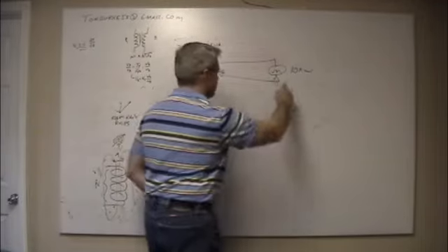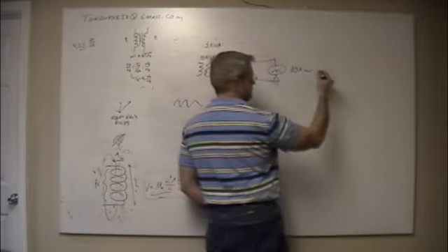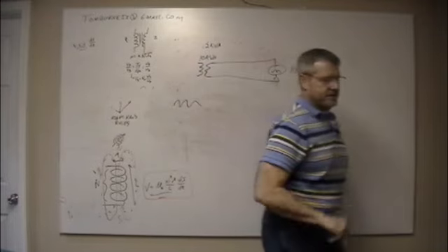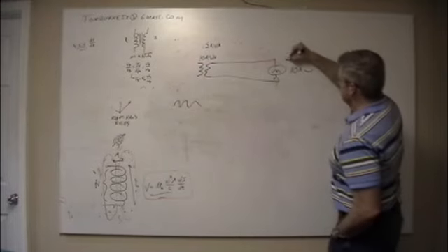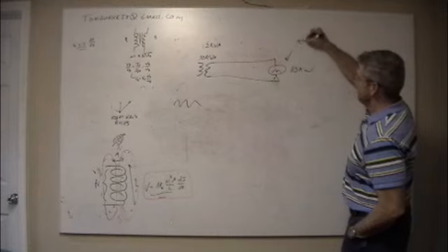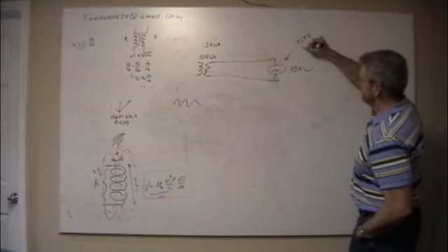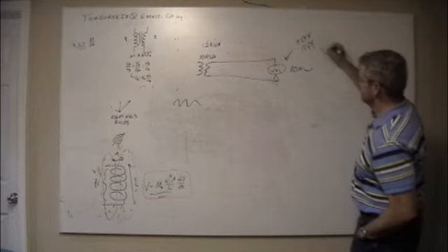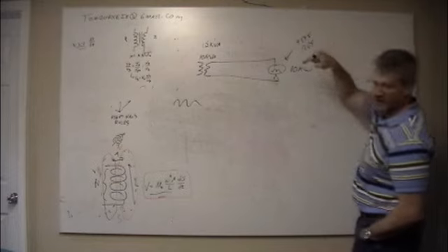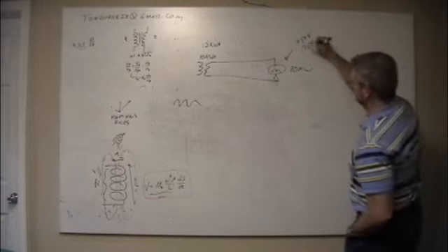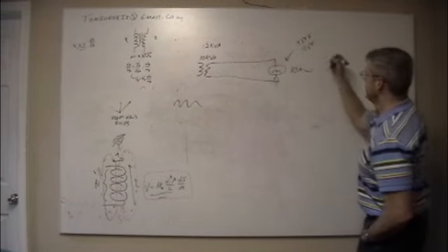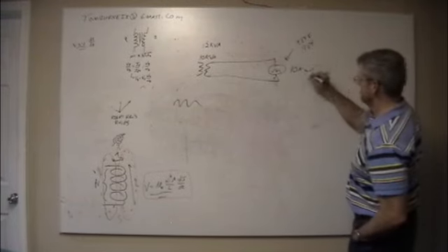So that means that my 10, you do this thing, right? A motor is about 0.9 efficiency, about 0.7 power factor at best, maybe 0.8 if it's really good, but 0.7 is a good estimation. So 7 times 9 is 63.